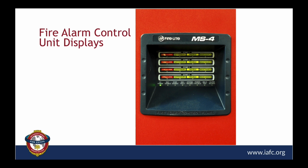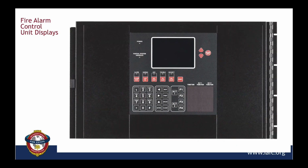And you can see the indications down below here are pretty much the same that we saw, other than now you're going to see something called a NAC, which is your notification alarm circuit. That's where your horns, bells, and maybe speakers could be connected. So once again, different panels go beyond the minimum to provide just a little bit more information. Let's go to the next display.